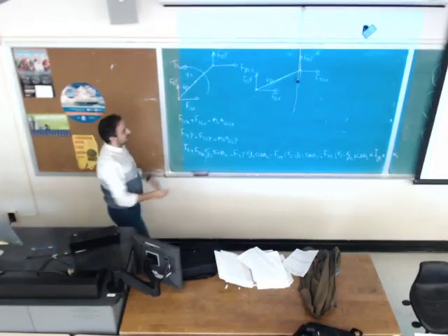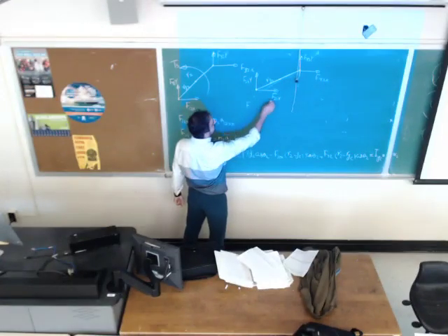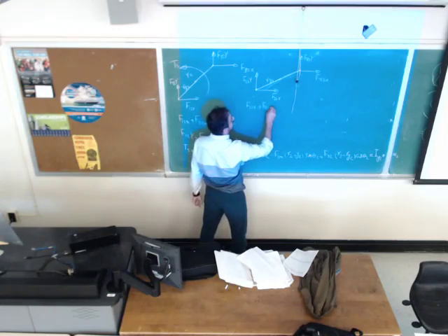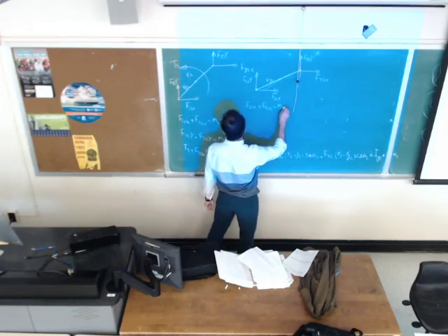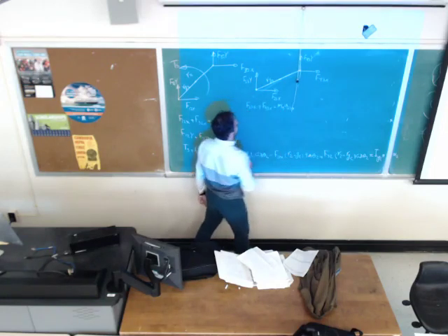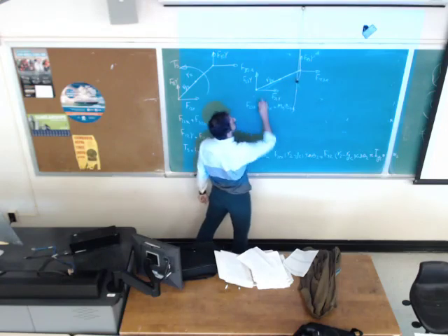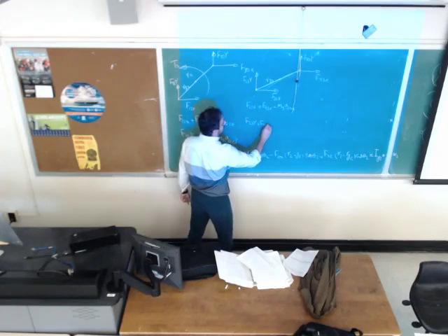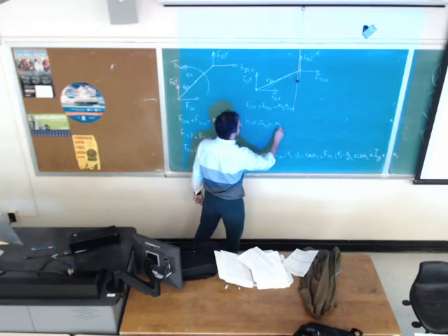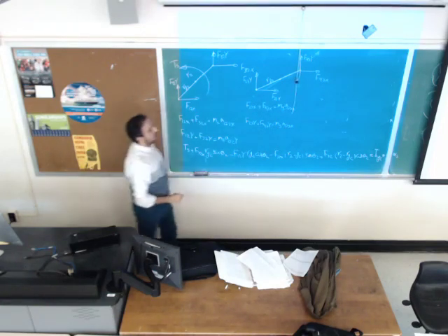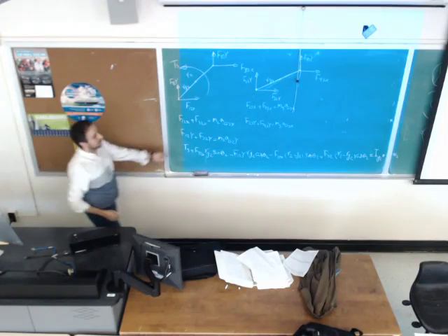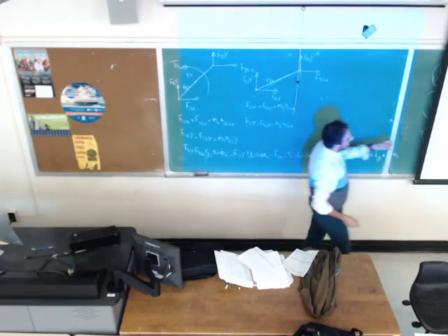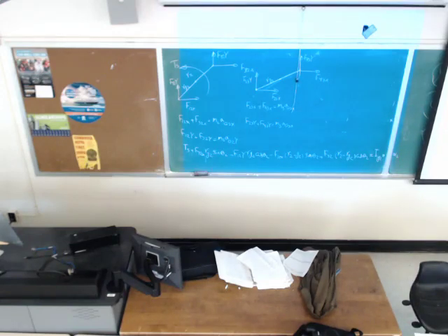Rewrite the force equation. Summation of the force in x direction, F23 in x plus F43 in x, equals the mass of link 3 times the acceleration of G3 in x direction. These two are in x direction, and these two are in y. The torque is going to be the same as this one, except we don't have TS, we don't have any external torque. I will start from this force. It's similar to link 2.